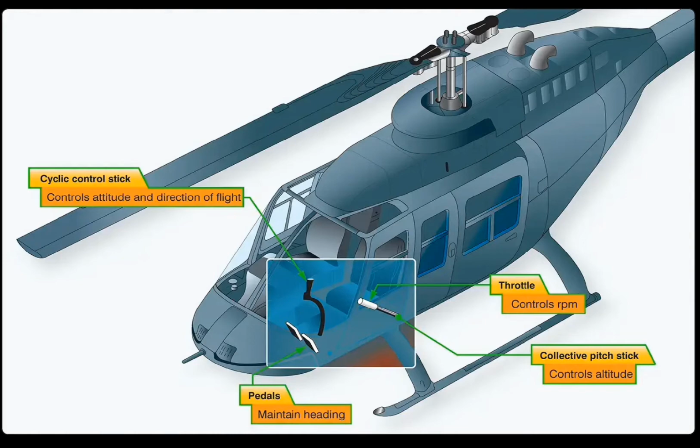Leading edge of the vertical stabilizer is offset from the longitudinal center line. What reference publications should be used to rig aircraft, including control systems? Aircraft specifications, type certificate data sheet, maintenance manual.